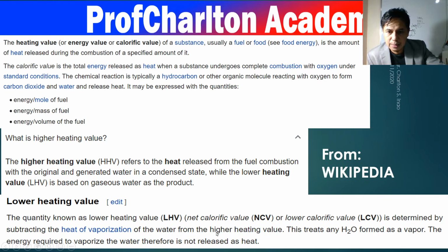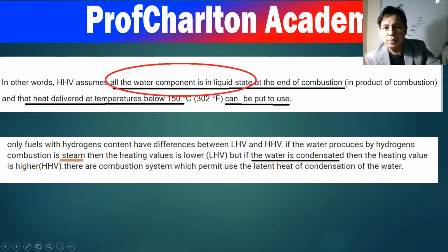Again, the lower heating value treats any water formed as a vapor. So as I told you, it's more on the vapor consideration, while the higher heating value is more on the condensed state of water, or the liquid. To emphasize again, the higher heating value assumes all the water component, as the product of combustion, is in liquid state at the end of combustion.